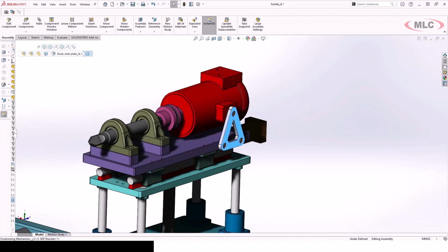And we could take our CNC machines out of service to run these parts on them, but then we're behind on products on the CNC machines as well. And we can't afford that. So that's really where the Markforged comes in and one of the biggest benefits of it. If I had a standard FDM printer, I might be a bit hesitant to print a metal bracket like this. But because Markforged can reinforce their parts with carbon fiber, and then on top of that, because I can simulate those forces and test everything out before I even start the print, I'm pretty confident that I can take this thing over at least to Eiger and run the simulation on it and see how it goes before resorting to the CNC machine.